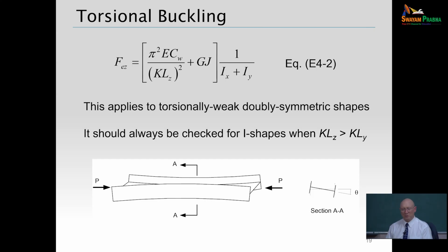But to get that, you would have to box in the ends. That would be one way to do it: you could fabricate plates and weld them on the sides of the section to restrain that warping. That would be rather expensive, to put in that material just to gain some warping restraint.